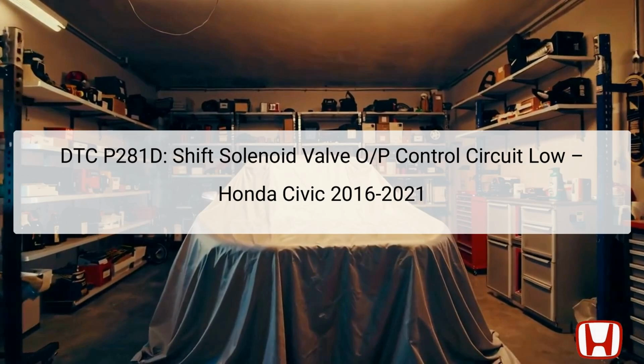The DTC code P281D indicates an issue with the shift solenoid valve OP control circuit in the Honda Civic models from 2016 to 2021. This diagnostic trouble code relates specifically to the pressure control solenoid H, which is responsible for managing the transmission fluid pump volume.